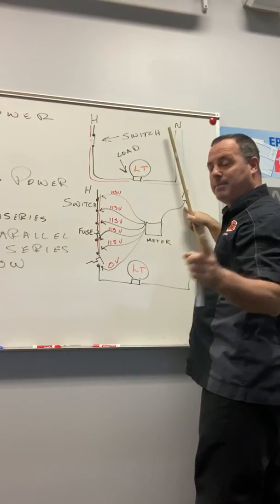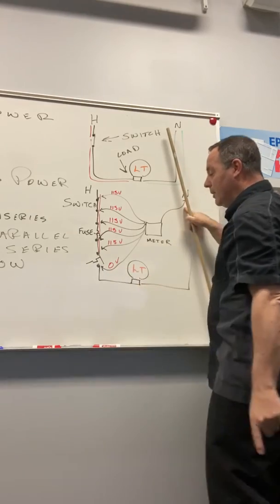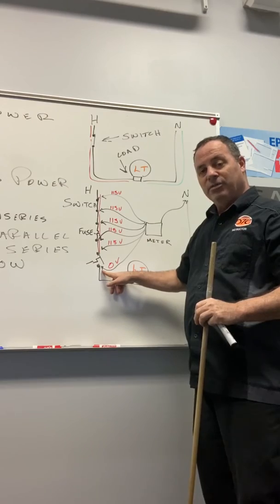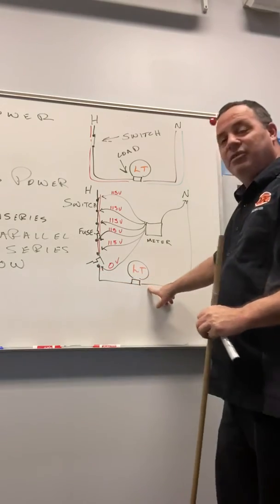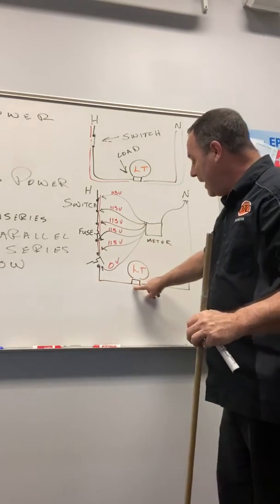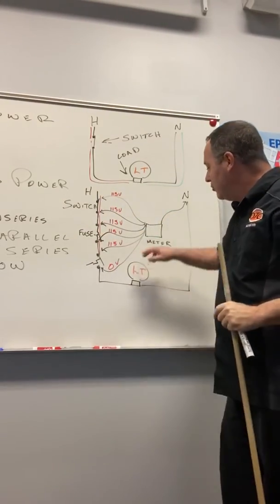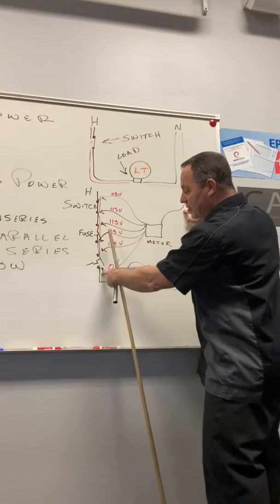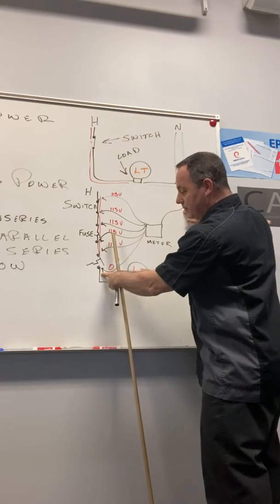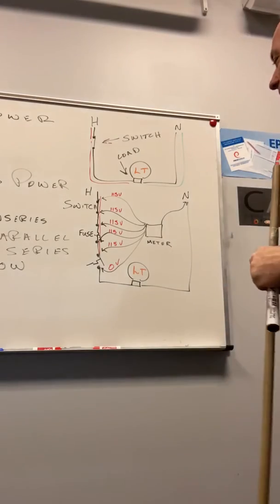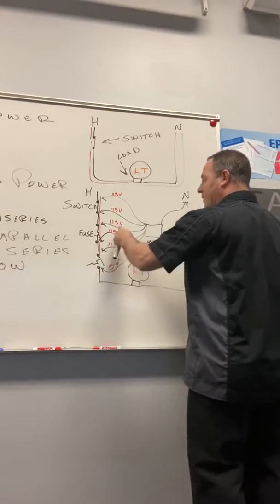However, notice what happened. The load, the switch right here is open. The thermostat's open. So the load is not getting the continuous path of potential power, potential voltage. So right here to this side of the thermostat, I read 0 volts. 0 volts. And that's the way that's read when you're in the field.